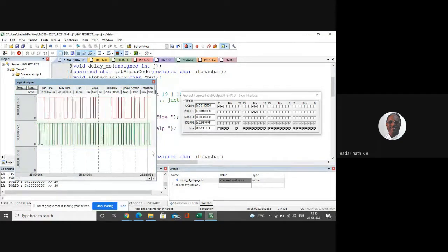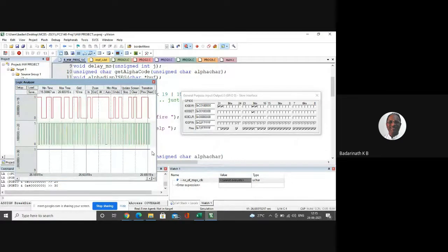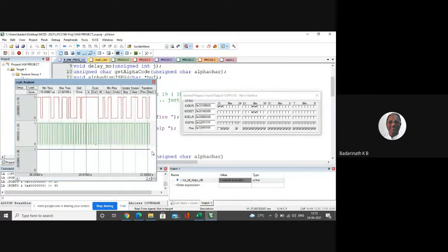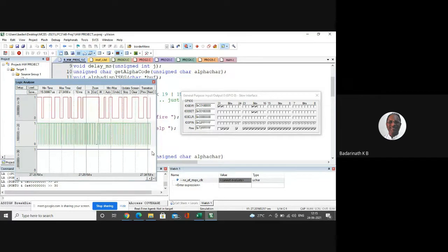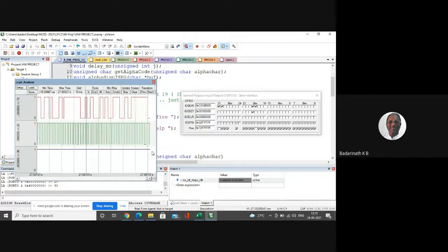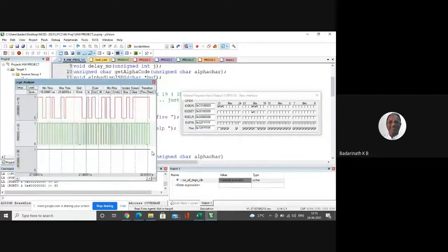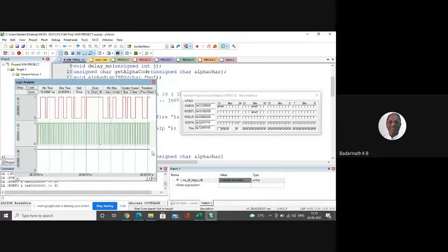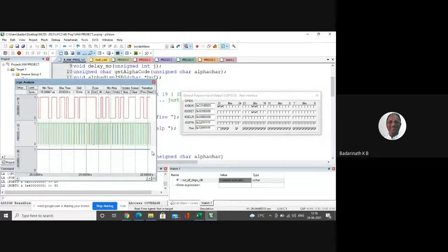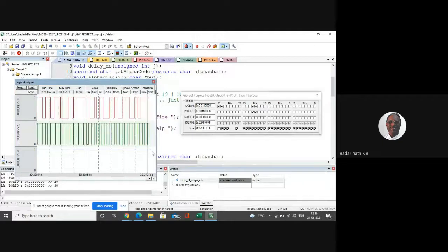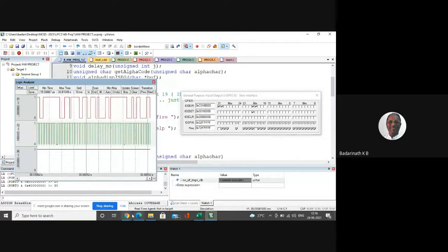So we will always use an alternate method of driving many digits using fewer pins. That is called the 7-segment shift register method. We have used it. For every one segment, we use one shift register as a memory to hold the data and give it to the 7-segment digit. By cascading, we can use the common lines of the microcontroller to push data into the whole set of shift registers as one device. We are treating the 5 shift registers as one set, one device. So this completes the discussion today.